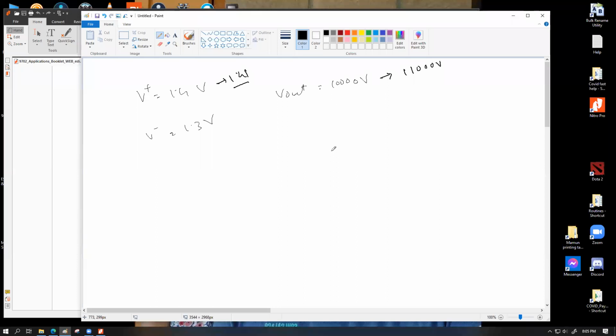The mathematical calculation is giving us this value for a certain small increase of the input. Now, what is going to happen for the realistic output, for the actual practical use of the op-amp? The earlier pair of values gave us an output of plus 9.0 volt. This calculation would also give us plus 9.0 volt. So the problem that we are coming across is that a change in one of the inputs is not reflected proportionally on the output side.